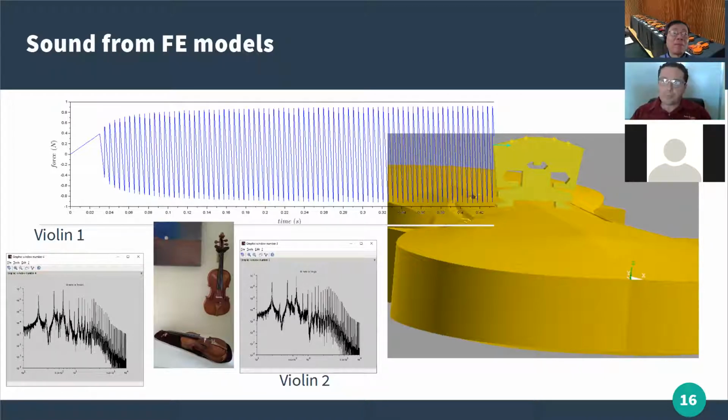I mean, we take the values of a simulation of a particular violin, and then we inject a sawtooth waveform, a very simple model of the force of the bow string on the bridge. And we are injecting this force with this blue vector that you can see in the bridge. And that's all. We are performing a transient, time domain simulation of this configuration. And in this way, we are calculating the sound of the G note.